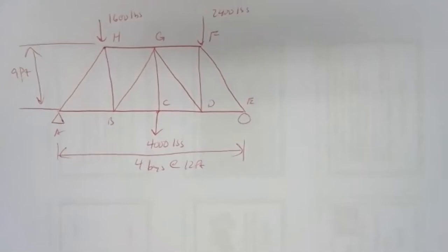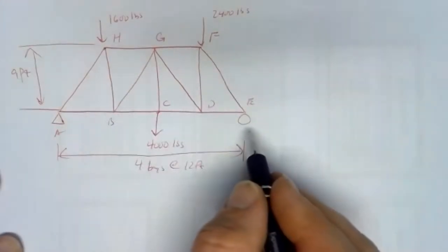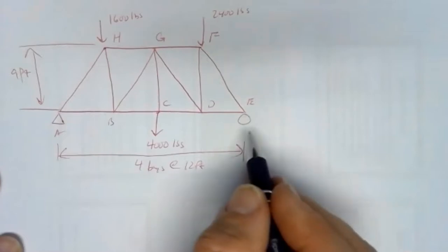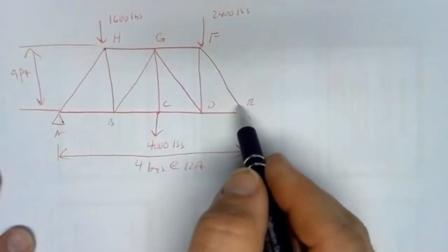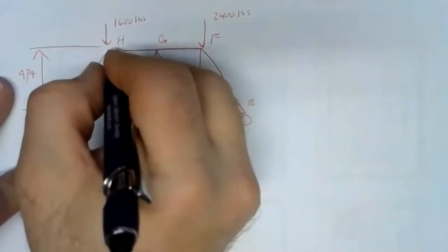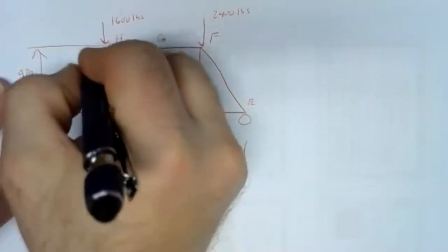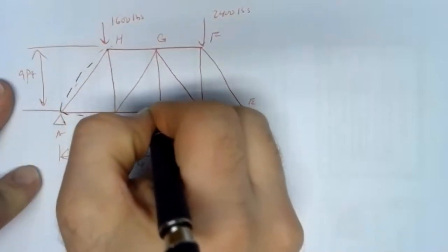Now, the first thing to do is find our external forces, solve the external problem. So even though this is a more complex truss than ones we've worked with before, the process is still the same. And in fact, we don't have to care at all about the internal structure of the truss to find the reactions. Essentially, our system boundary looks something like this.